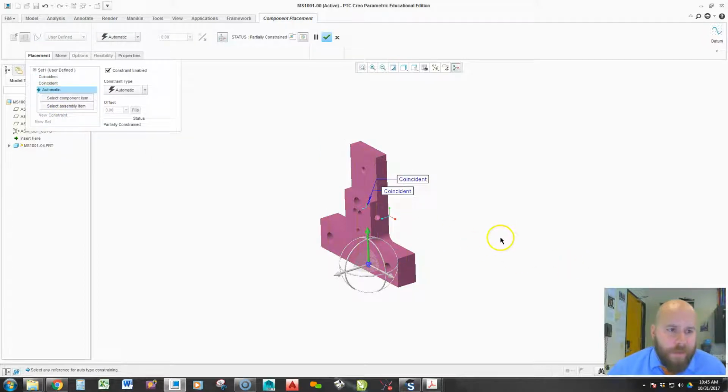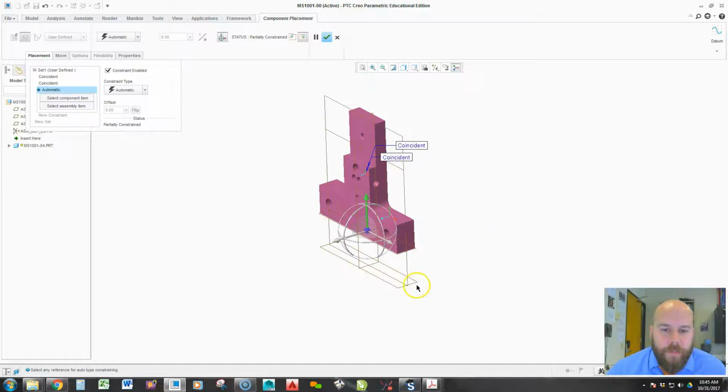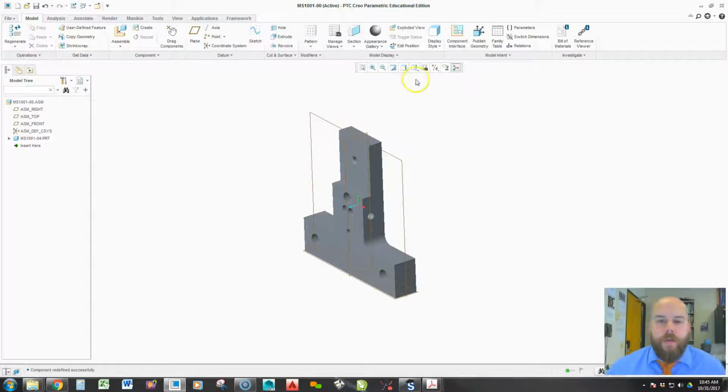And a lot of times what I'll do, rather than just hunt through the other constraints and try and make sense of it, is I'll hold Control Alt right mouse button, and now I can see it moves up and down. So that would give me a clue that I need my top planes to be assembled. Now I'm going to middle mouse button click again. That's just going to automatically click this check mark. Anything that's blue gets selected by doing that.